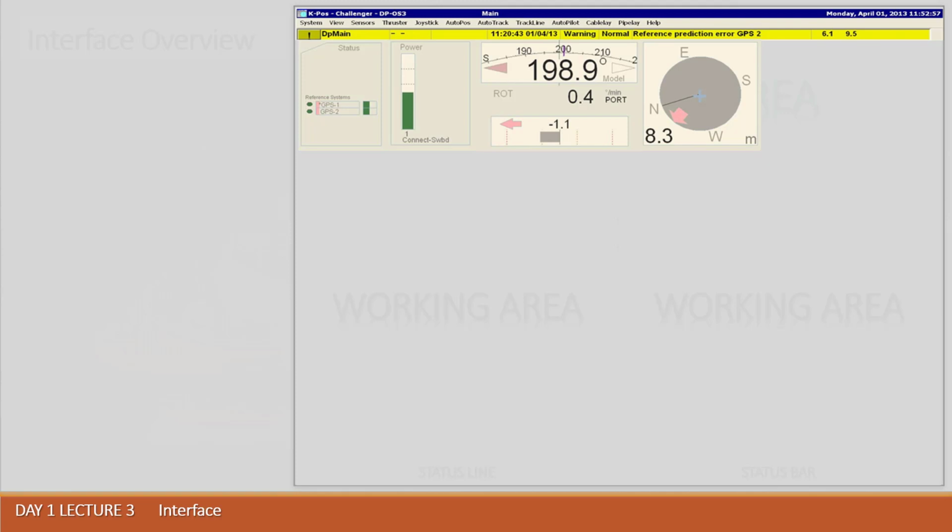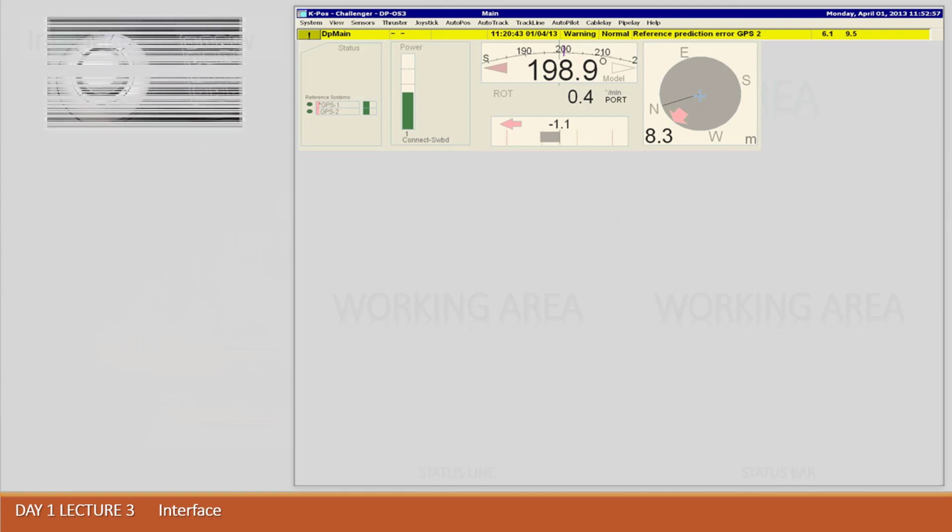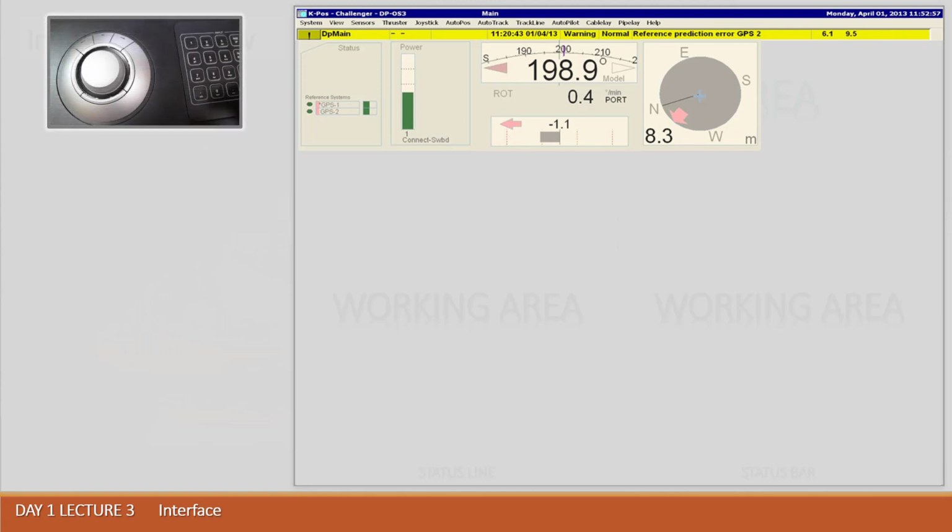Our heading wheel may be used for heading control in auto position mode. Center click, I remind you, is to call the menu. Scrolling of the heading wheel adjusts the value for the heading setup. Then arrows may adjust the decimals of the heading value parameter. And the buttons around the heading wheel are also click sensitive and may be tuned up to adjust the rate of turn and wheel over point distance, for example, for autopilot mode.